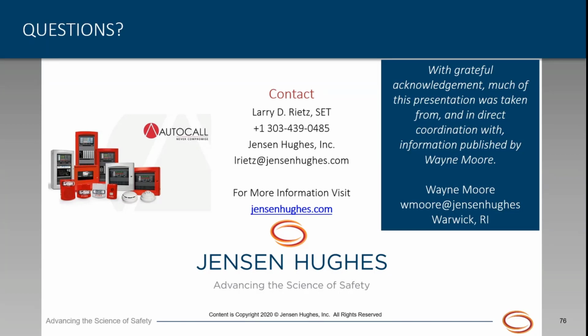Okay, and the final piece of that was, are there terminal cabinets that are rated for 2 hours that can be utilized? That's a great question. I'm going to answer it in kind of a cheater way. There are terminal cabinets and junction boxes that are provided by the manufacturers of survivable cable that should be used with the survivable cable installation. I do not believe those terminal boxes or junction boxes in and of themselves carry a 2-hour rating. I could be wrong about that, but to my knowledge, that does not exist.